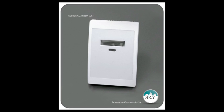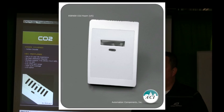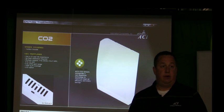CO2 sensors, we have, again, probably our number one product that we get involved with gas detection. 4 to 20 milliamp, 0 to 10 volt, or 0 to 5 volt, all jumper selectable right on the circuit board, which is nice. It also has a relay option or LCD option. And then we have that for wall mount or duct mount, and we also have outdoor air mount. So that seems to be something that's going to be specified more and more in building plans and new buildings, is outdoor air CO2. So we do have that available in case you ever have a need for that.